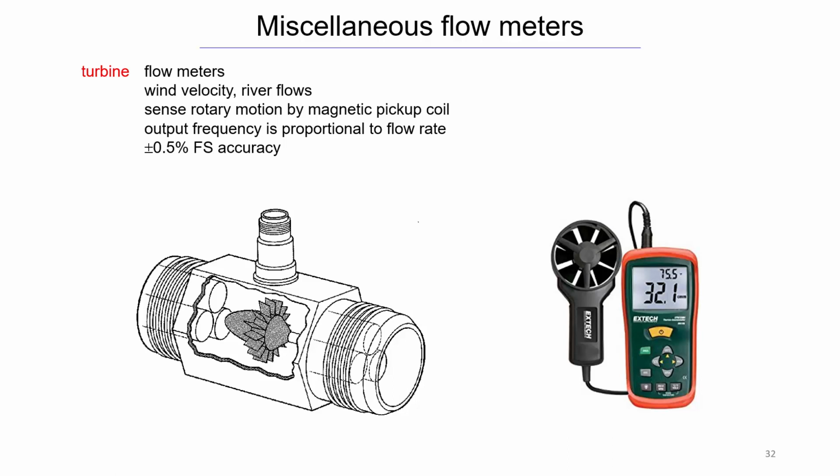But generally what a mechanical engineer doing that job will use this for is, once their design has been built, they'll go around and use this as part of the testing and balancing. So just making sure that all the right airflows are coming out of the diffusers of their system. Maybe all the dampers have to be adjusted to balance the system if they're not getting what they designed. It's one common application of this for mechanical engineers.